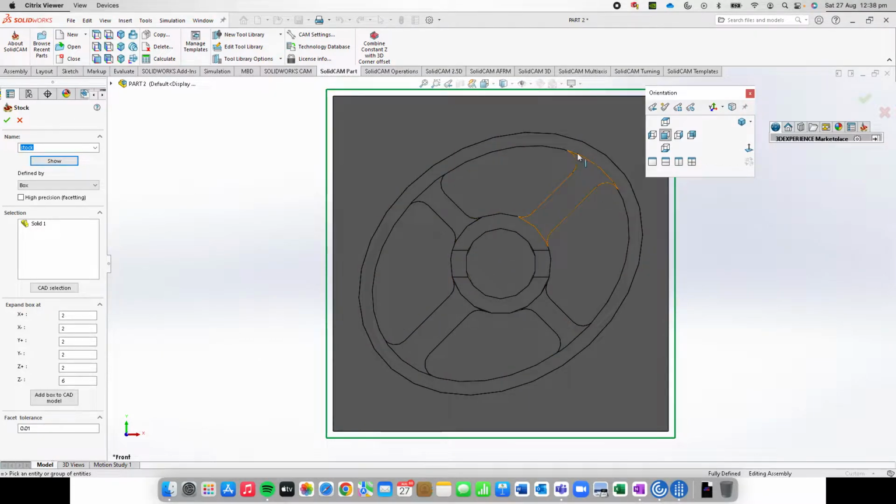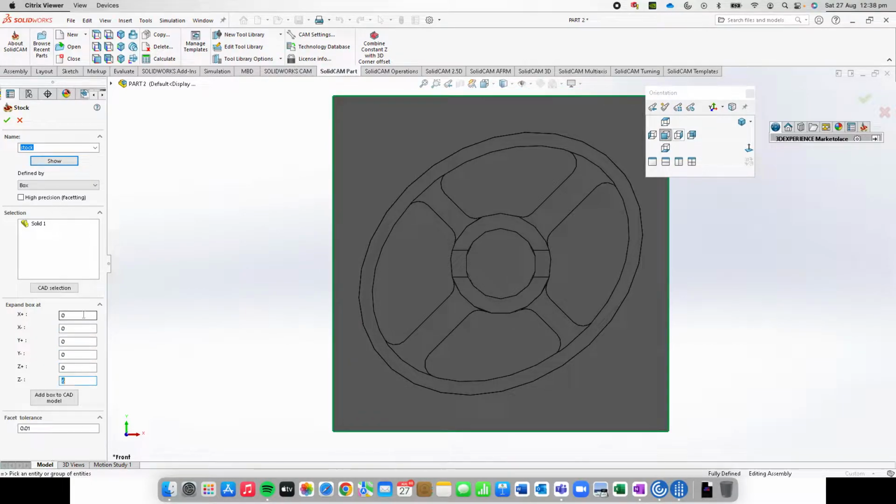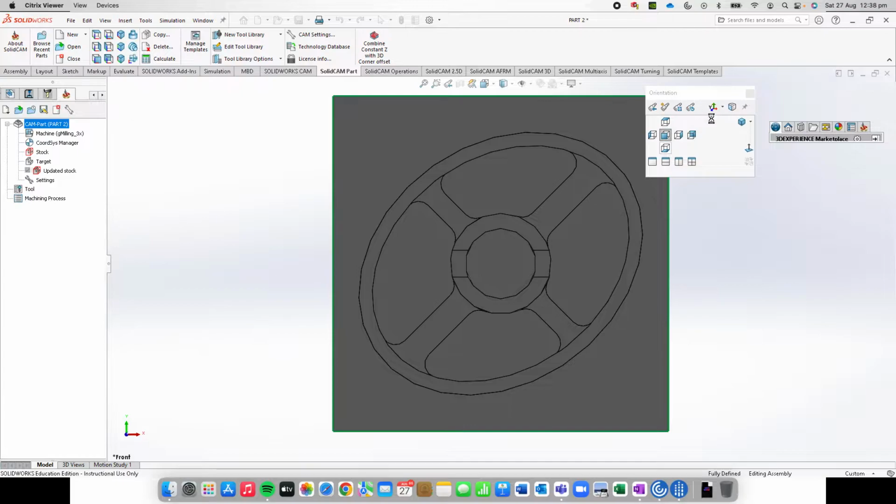In the real world, this will be ideal because you want to remove some of this material around the outside to get those perfect parallel surfaces and a nice surface finish. But for today, I'm just going to specify the geometry to all 0. This will just make it easier so we don't have to do those finishing cuts. So once we define the stock, we can select.